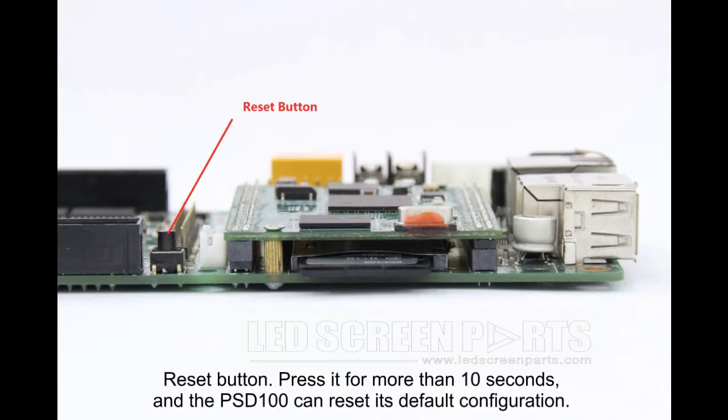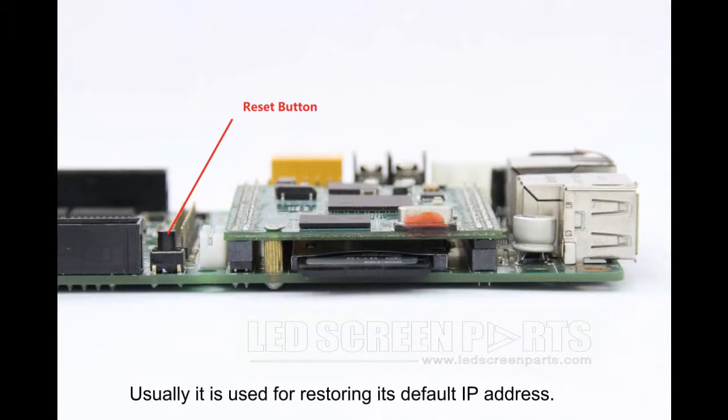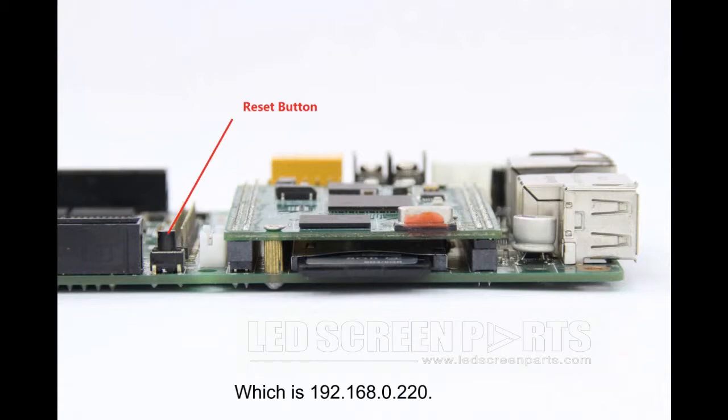Reset button. Press it for more than 10 seconds, and the PSD100 can reset its default configuration. Usually it's used to restore its default IP address, which is 192.168.0.220.